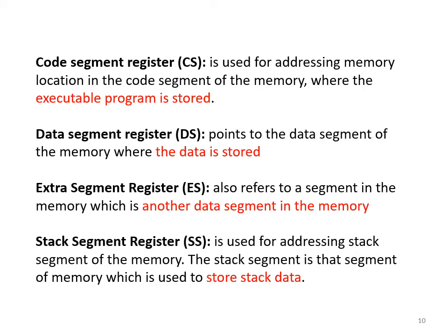When a call instruction is encountered, the 8086 will move to the address of the subroutine, that set of instructions which constitute the add numbers subroutine, and it will execute that. After that, suppose you have another instruction like move AX comma 10, where you are moving the value 10 to a register called AX. So once you finish execution of that subroutine, you need to come back to the next instruction after the call, that is move AX comma 10.